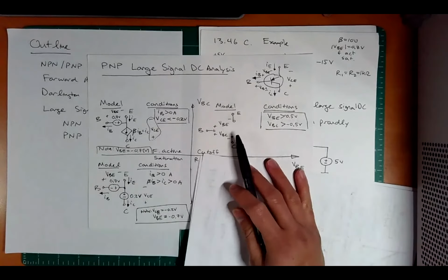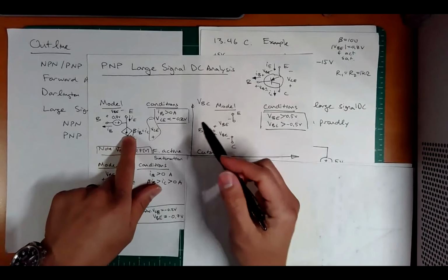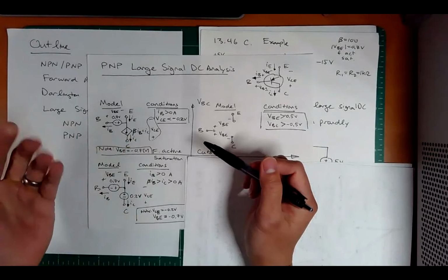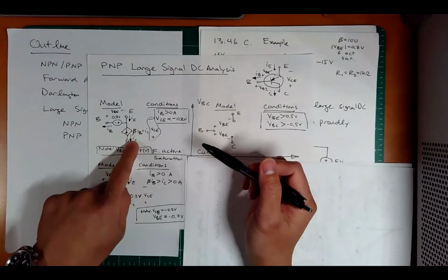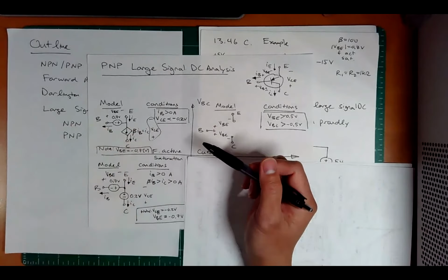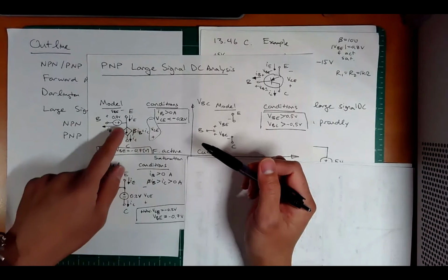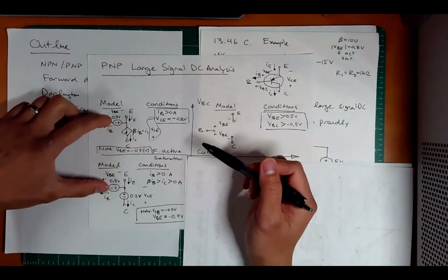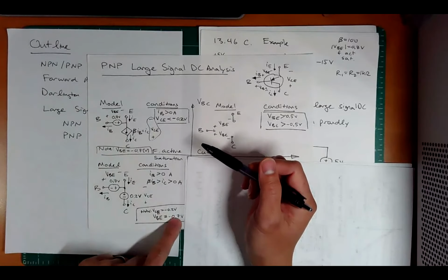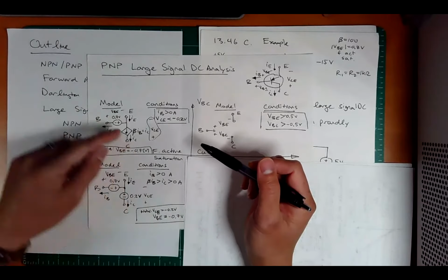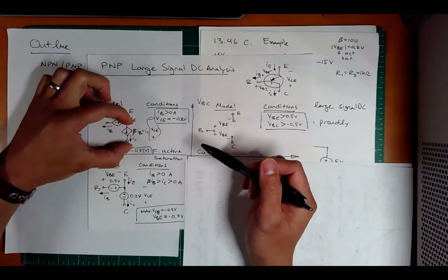And the forward active one here, again, we have a current controlled current source. And that should make sense because IB and IC are related, and IC is actually IB multiplied by that gain. All right, so not too bad. Same model, same 0.7 here. Again, VBE is negative 0.7, so we can't mess that up. And notice VC is the voltage across that dependent source.